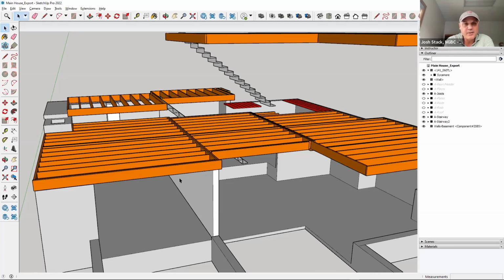As we look at all the issues of electrification, I know we're focusing here on the duct distribution for this particular house, which has an open floor plan and a couple of concrete shear walls that don't show in the model right now, on both two stories, solid concrete, that also pose some challenges. But the client's goal is really a fantastic one, to go all electric. And so we're trying to solve this distribution problem so we can achieve that for them. That's excellent news. The use of the drop beams hopefully opens up the path to run branch ductwork down between the floor joists. So I was glad to hear that.